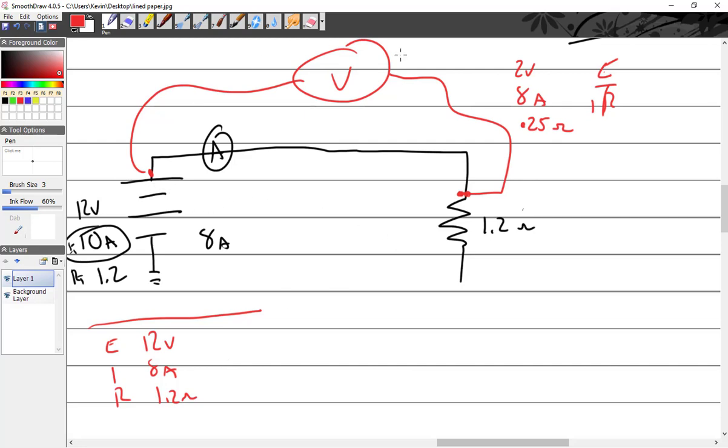You can figure out the resistance of anything that's unknown by measuring the voltage drop. So rather than saying, what's the resistance of that? Well, hang on, let me take the whole airplane apart and measure that. I just turn it on and do a voltage drop. Okay? Perfect example. I'll give you one more. This is something maybe you can relate to. Maybe not. You have a car. You have a car battery.